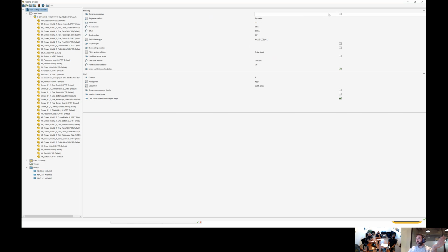And here we are going to detect directly which boards are usable for this project. In our nesting, we can manage different parameters. Here I've used a half-inch tool and an additional offset to separate the parts. And I'm going to use cam information from the SCM Xylog cam program on the parts we have seen just before, and position all the cam information in the sheet with the best position and the best optimization. I just click on rebuild.